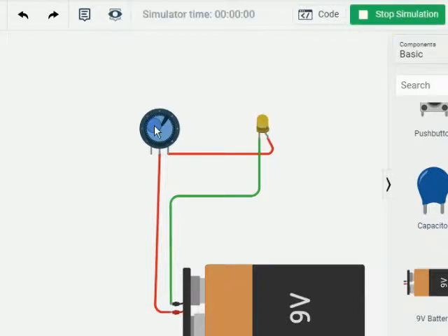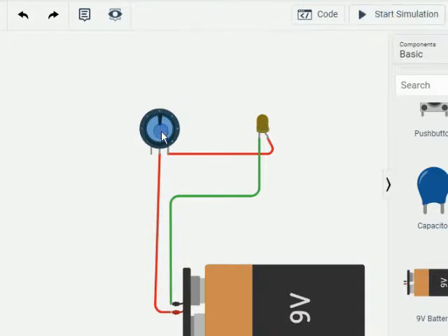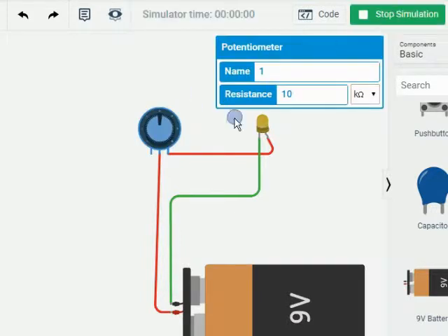All right, so let's stop the simulator and make sure that this worked. Okay, stop the simulator, click on it, 10,000 ohms. Let's start the simulator again, and now look. You can see now that we're controlling the brightness. But when we go too little or all the way to the end, we're making contact from this pin to this pin, okay? Because from here all the way to here is 10,000 ohms. But when I come all the way straight, you got to pretend that the center of this wire is connected to this part of the knob. So once we go here, we bypass all the resistance, and then look what happens to the LED light.